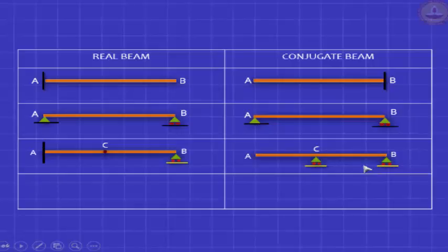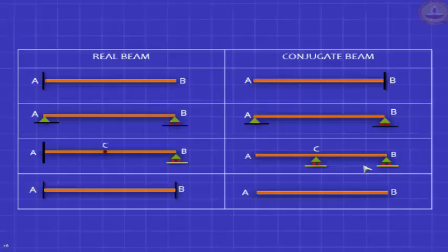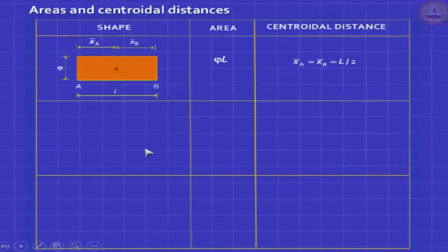And here's the funniest of the lot. Fixed beam. The conjugate beam is free beam. Then you'll say, how will this structure stand? Well, luckily for you, it has to only stand in your imagination. But real structures also are like this. The aeroplane, for example, the helicopter, they're able to stand. But they are self-equilibrated, right? So don't break your head too much about this. This is all your imagination. This is reality.